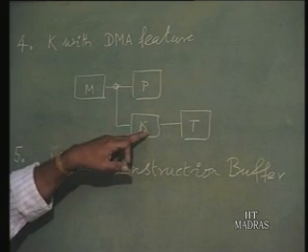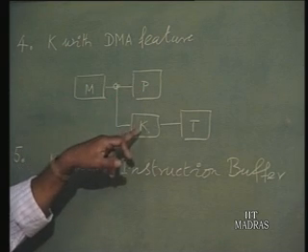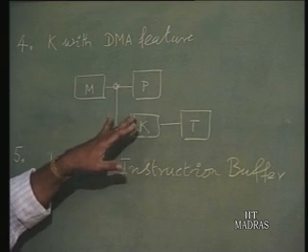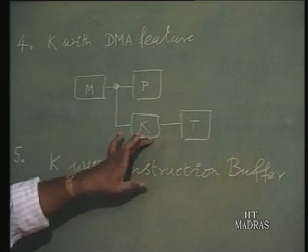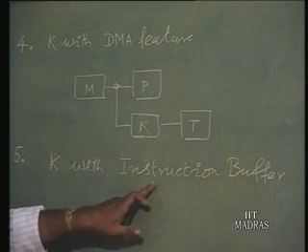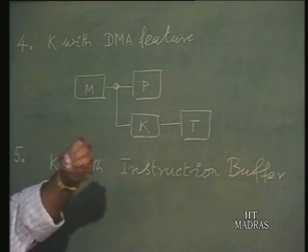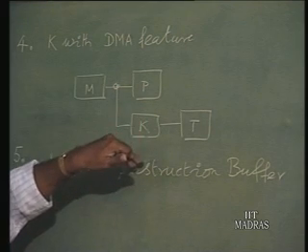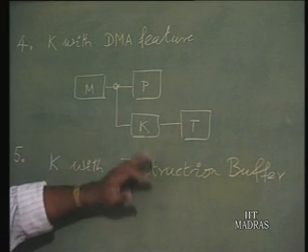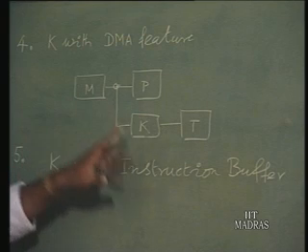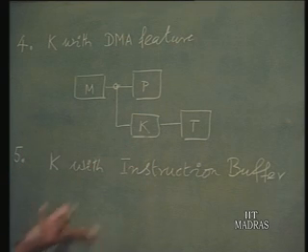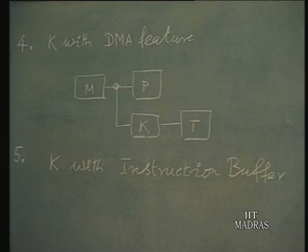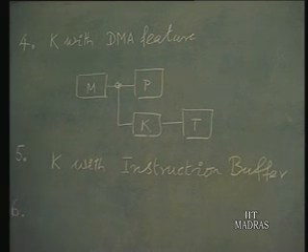And before the DMA takes place, the processor issues some commands, rather, we can say, issues some instructions. Now, in this particular case, the processor issues quite a few more instructions, and the controller has the instruction buffer, and during that particular access it will execute those things. Just a little more complex situation.